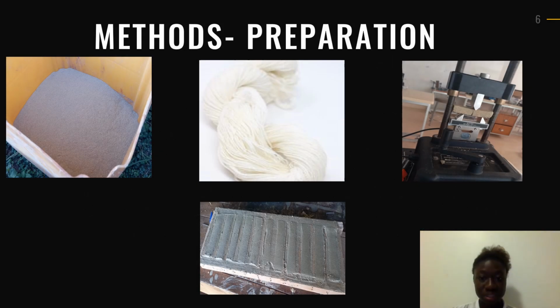Clay ores were physically pounded and sieved into powder, and then the clay was reinforced with fiber. The fiber was cut between 2 centimeters and 3 centimeters long. Only clay was cast as the control experiment, but the samples themselves were 60% clay and 40% fiber. This was by volume proportion. Also, when the mixture was made, when water was added to the clay only and the fiber and clay mixture, this was cold worked for 3 days before being cast.